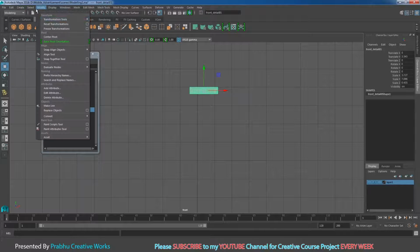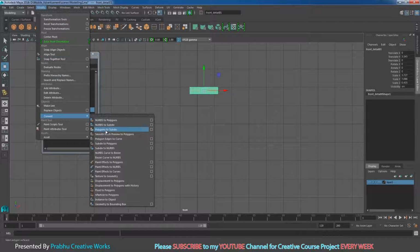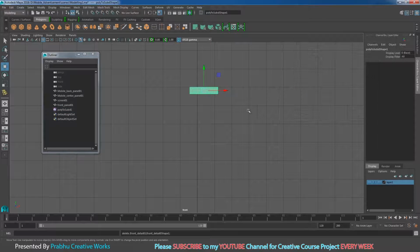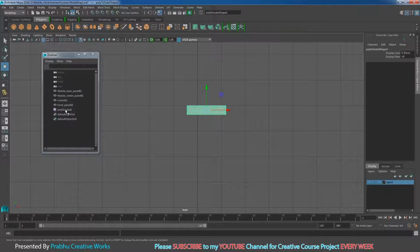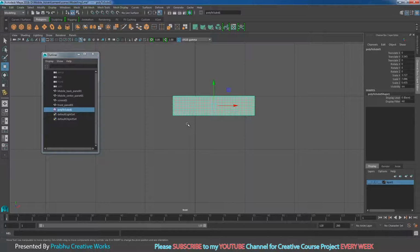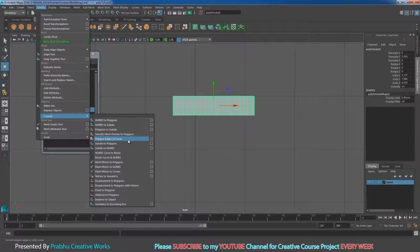Now go to modify, convert and choose first of all polygons to sub D option box. So I will reset my settings. Here you need to increase the slider all the way up. Here also you need to increase the slider all the way up and choose create. So see here our polygon has changed to sub D. So now you want to change this sub D to NURBS. I will select my sub D object, go to modify and choose convert. Here you have the option sub D to NURBS. So I will click on that.